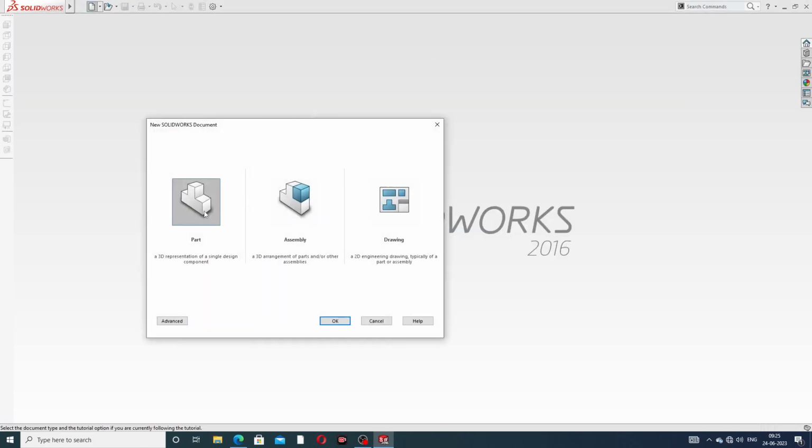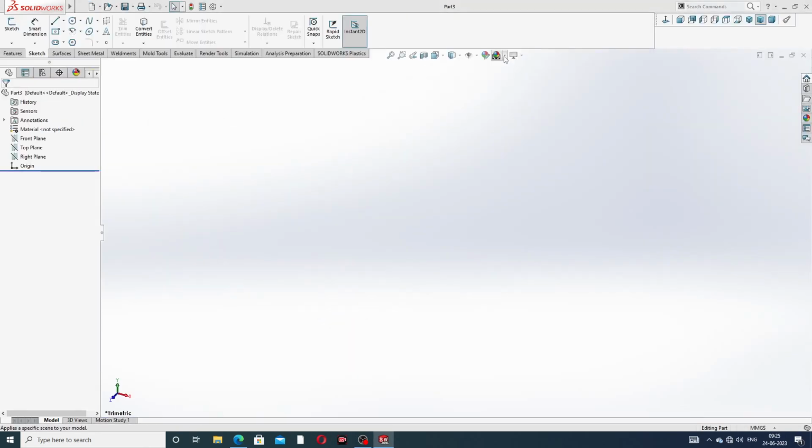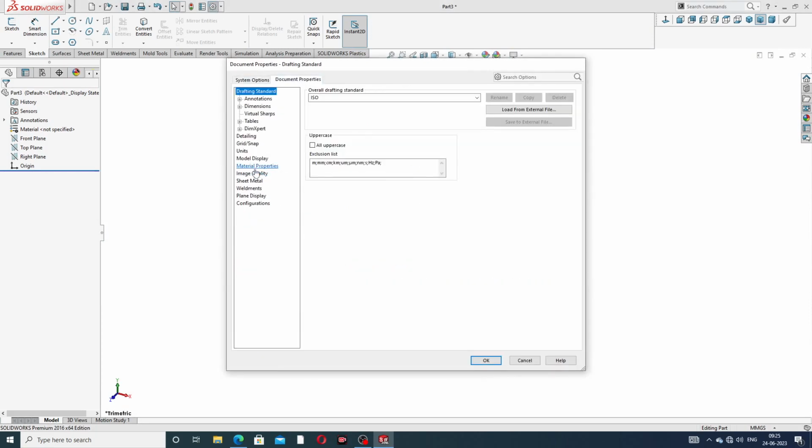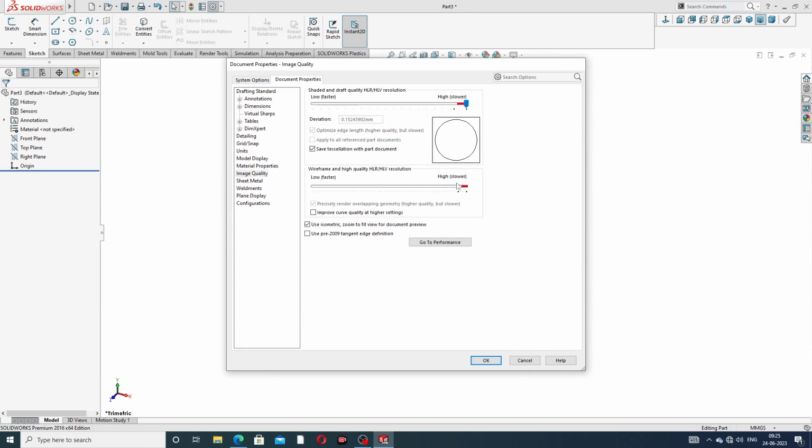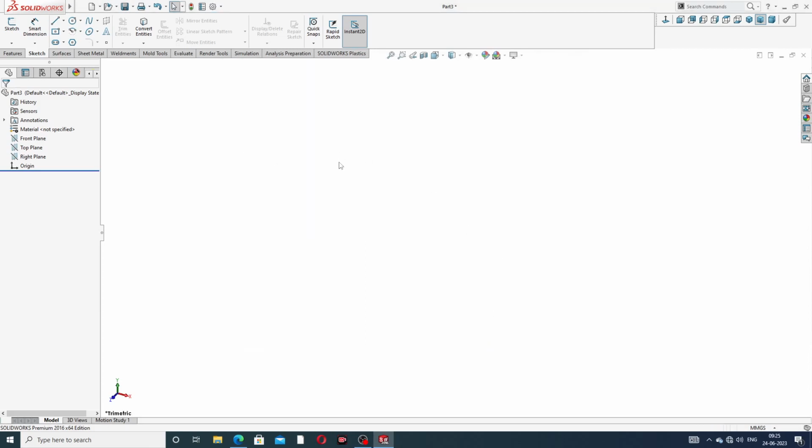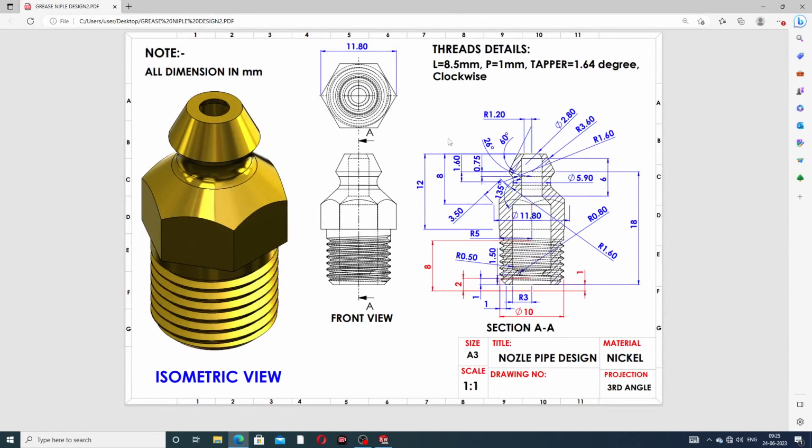At first select a part, and a very important point is to use the plane white and adjust some settings, so the image quality is very high because this body looks perfect. Next, the geometry is defined: this length is 18 millimeter, draw a circle of 3.6 millimeter, this gap is 3 millimeter, the full length is 10 millimeter, but the half-length diameter is 5 millimeter.